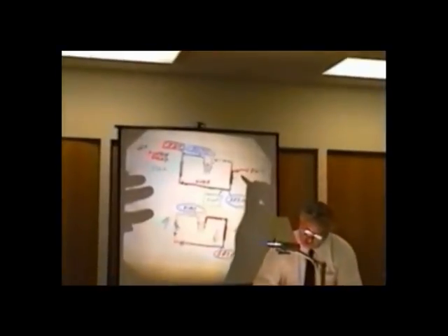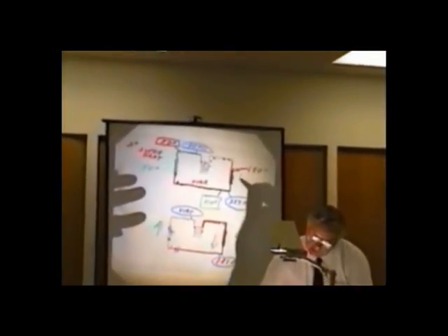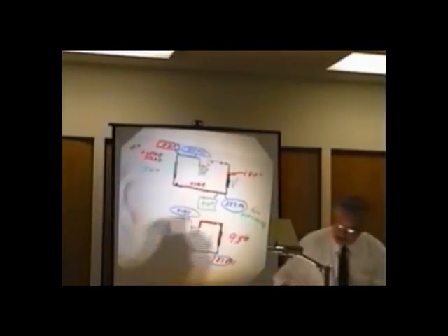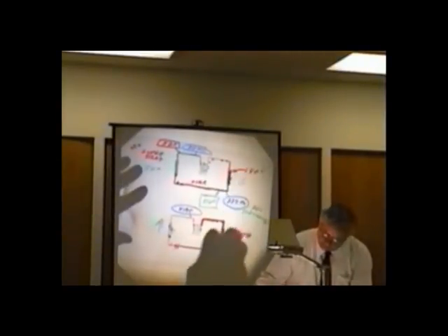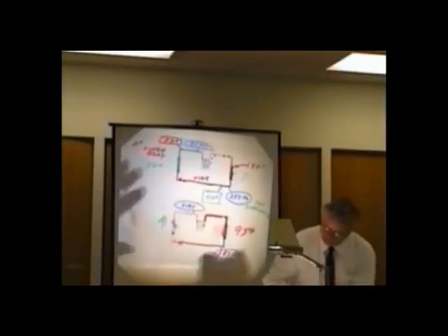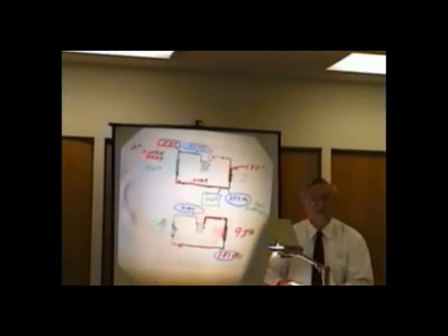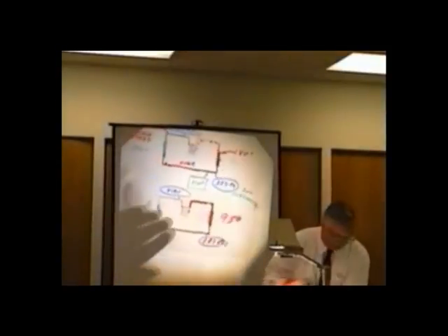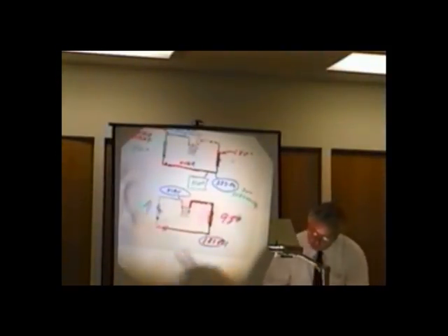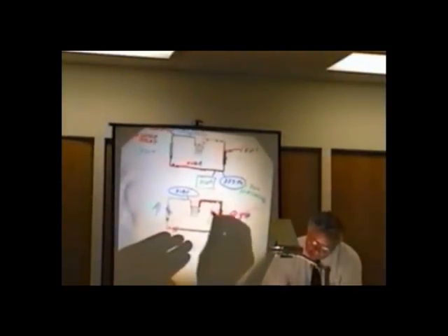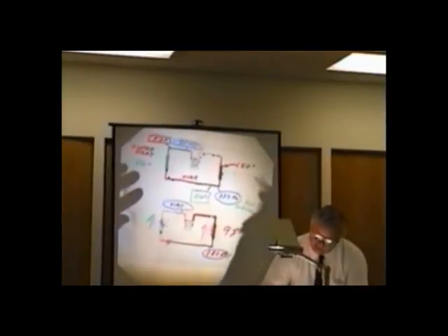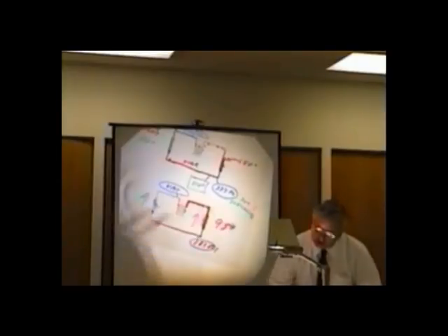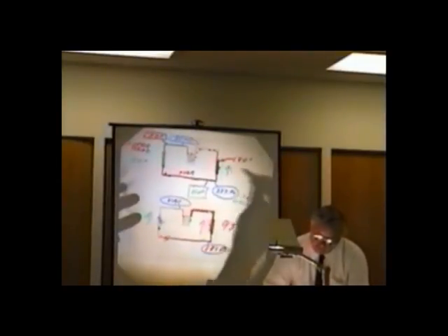When we did an overcharge, the subcooling went down. What am I talking about? You're confusing me. Reversed, sorry. This is why live classes are so much easier than video. But these things happen, and they happen in the field. Subcooling goes up, because when we did the overcharge on the high side, it went up, correct?